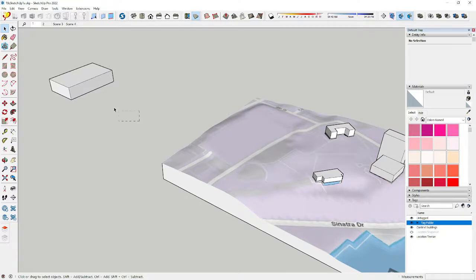I'm typically going to want to group that. So I select everything, left-clicking and making a box from left to right. The reason I go left to right is because it will only select the lines that I completely select. So if it's in the middle of something else, it's an easy way of selecting it. If I go right to left, it'll select everything that it touches. Anyway, just play with it. If I right-click and make a group, now this thing's a unit.